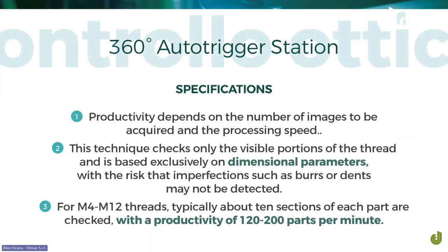Now, let's talk about performance. With this technique, the more images we acquire, the greater our ability to detect defects. But there's a trade off. More images means slower throughput. So we're always balancing detection sensitivity with production speed.